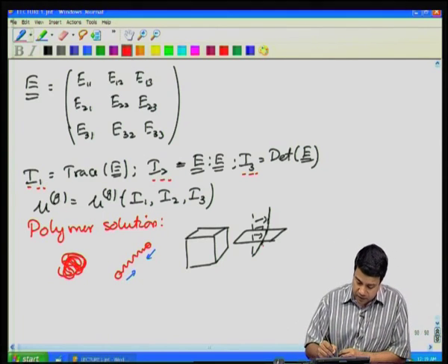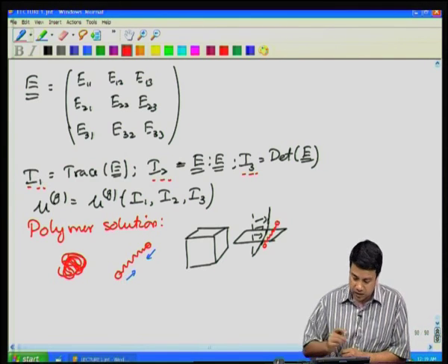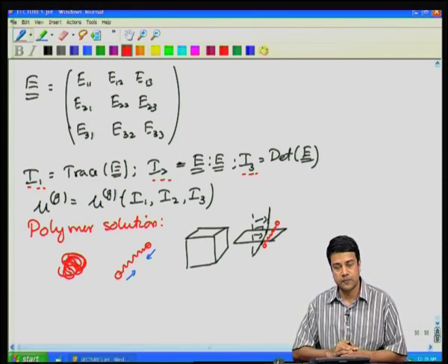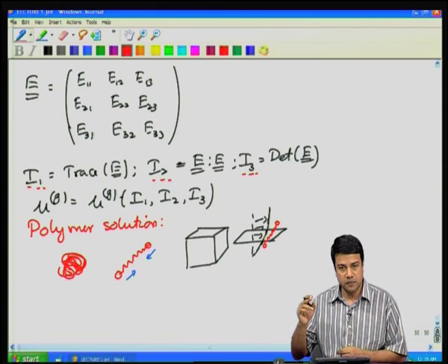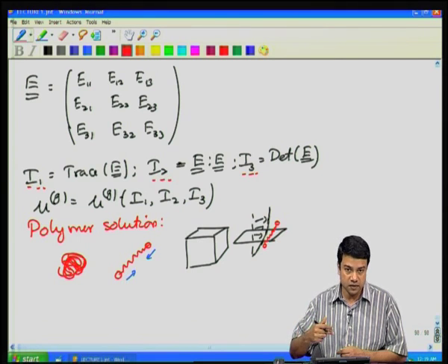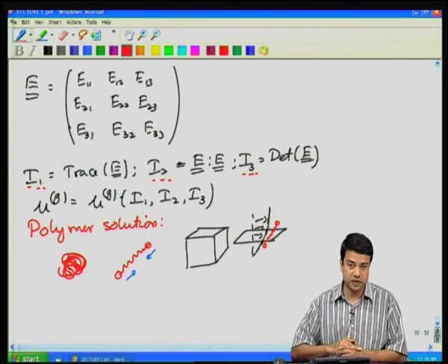However, I could also have a transfer of momentum because one end of this bead is below the surface, and the other end of the bead is above the surface. So, the end of the bead above the surface exerts a force on the end of the bead below the surface, and that is a net force that is exerted on the volume below the surface. Okay. So, the presence of these polymers results in an additional force. There is a stress tensor due to this force.